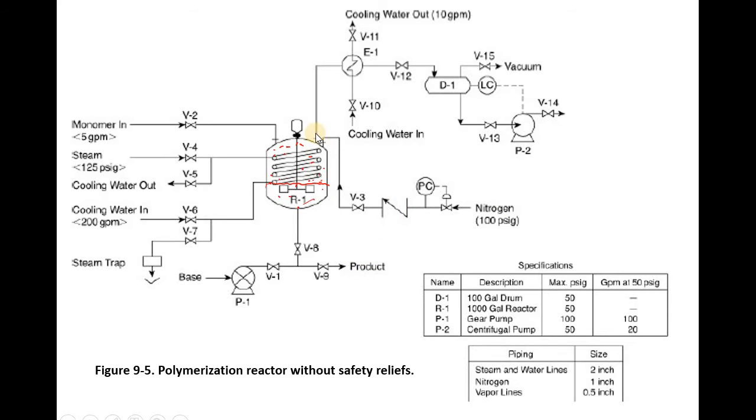And what do we have? We have some kind of inerting. You're adding nitrogen just to make sure that you don't have any collective mixture of any cloud, explosive cloud. And actually this is not for every monomer. Some monomers are very safe to use and you don't need that nitrogen. But talking about industrial processes is different than lab scale.